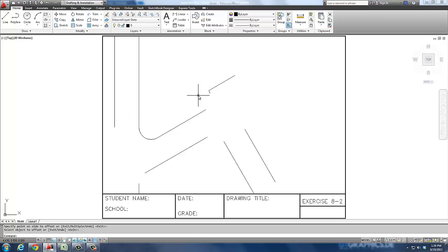It doesn't actually tell me. I'm looking at the drawing to decide what it's supposed to be, what it calls it in the drawing itself, and there's really not a good explanation. They call it site plan, so I'm assuming this is supposed to be streets and a driveway and a couple of other streets. So I've just offset those lines that distance right there, which is the distance of a roadway apparently in this scale. So I've just got those out there.